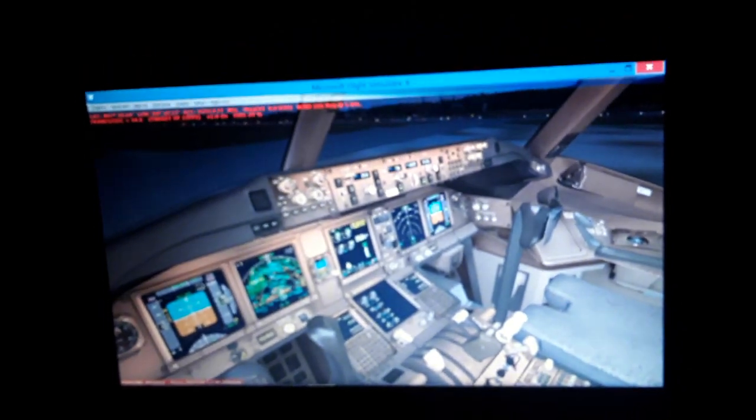so some principles about flying, about the lift created from the wings that overcomes the weight of the aircraft, and the thrust from the engines overcomes the kinetic and static friction in the aircraft. We have 254,000 kilograms of takeoff weight, or about 531,000 pounds, which is below the maximum takeoff weight. We have only about 30% of fuel on board, making maximum takeoff. So we're gonna make the calculation for the takeoff speed.